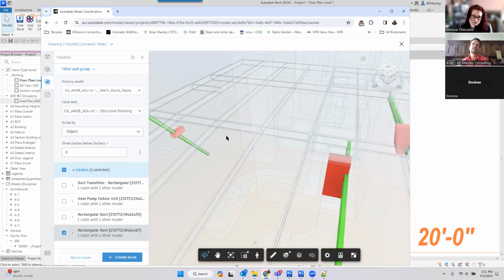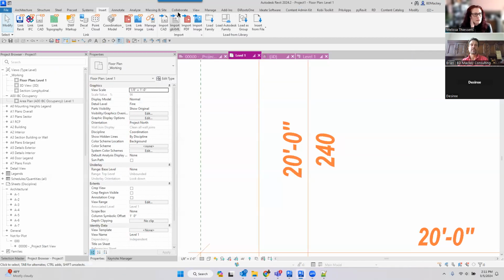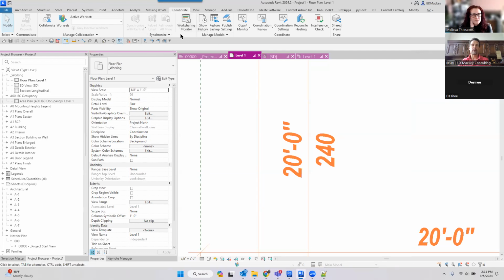Yes, and Dan's pointing out that you can have the views and publish settings all set up in your template, so you don't do that every time, which is definitely helpful. Yeah, so if you're in Revit, I can't do it now because this is not a collaborated model, but in here you would have publish settings. In those publish settings, you would say, hey, which views do I want to be published? And you can create different publish settings, by the way, too. So you can create one just for model coordination, as well as one for sheets, as well as one for other views. And you can toggle on more than one publish setting to be published when you hit it. I have clients who do all their sheets and they're all separate publish settings, so they don't have to keep track of them all in a single one.